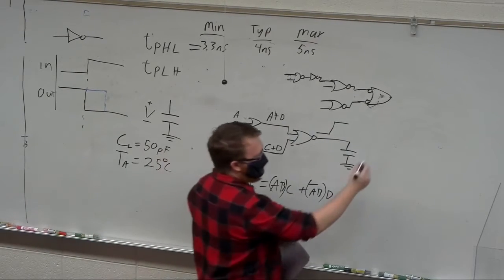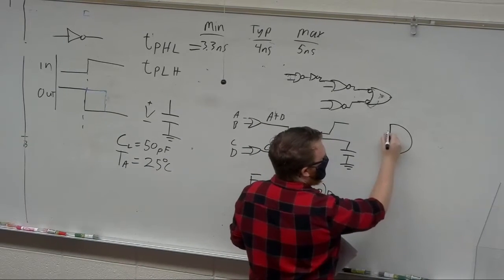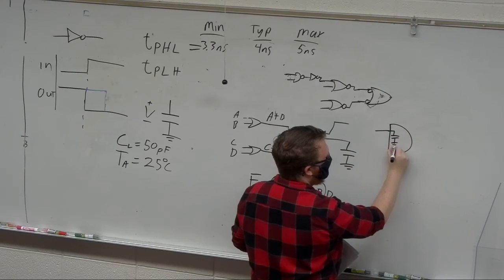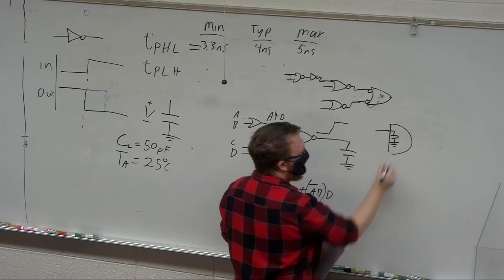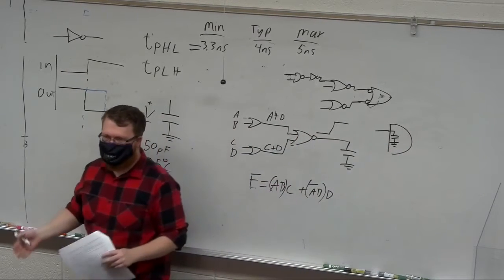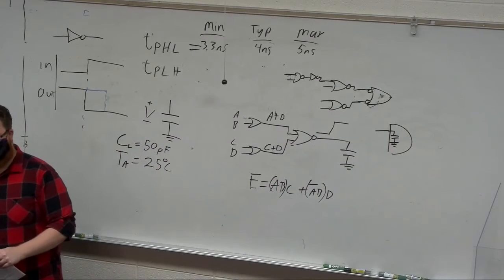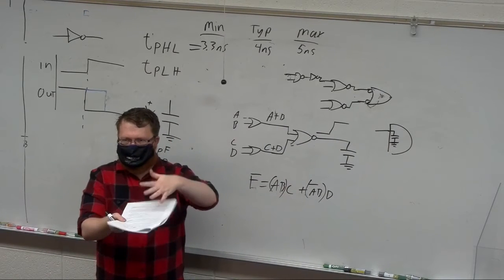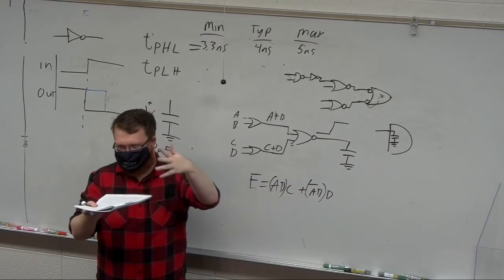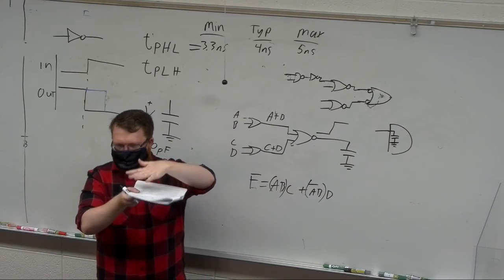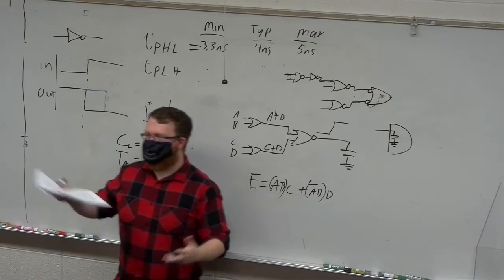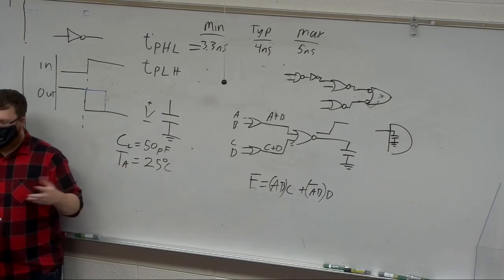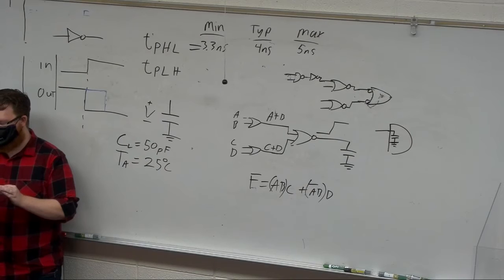These capacitors happen because if you looked at a gate at an input terminal, there is actually what we would call, that's a ground, parasitic capacitance. Ideally, they would have none, but capacitors are just formed by parallel plates of metal. So your device has sheets of metal in it, or silicon, right? And between those two, you create capacitance. You end up with parasitics. You'll delve into these parasitics in several of your classes, but that's what it's causing. So when you're doing that, you need to know how many devices that you can connect up to.